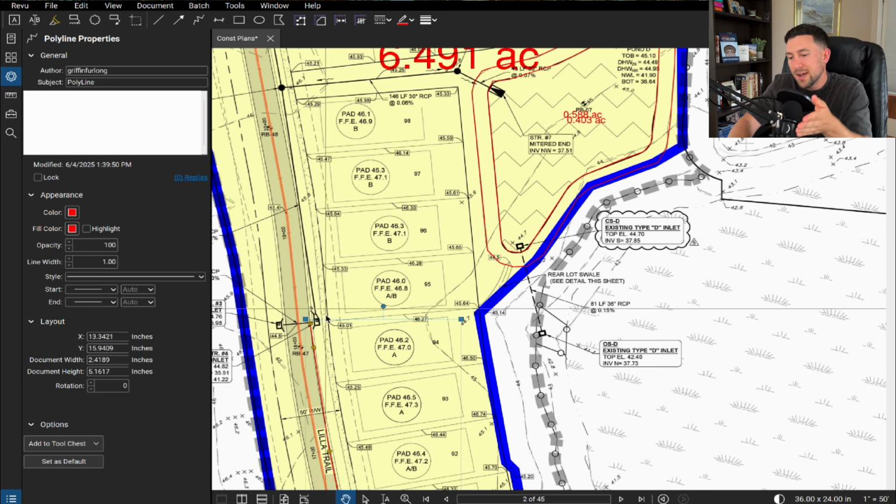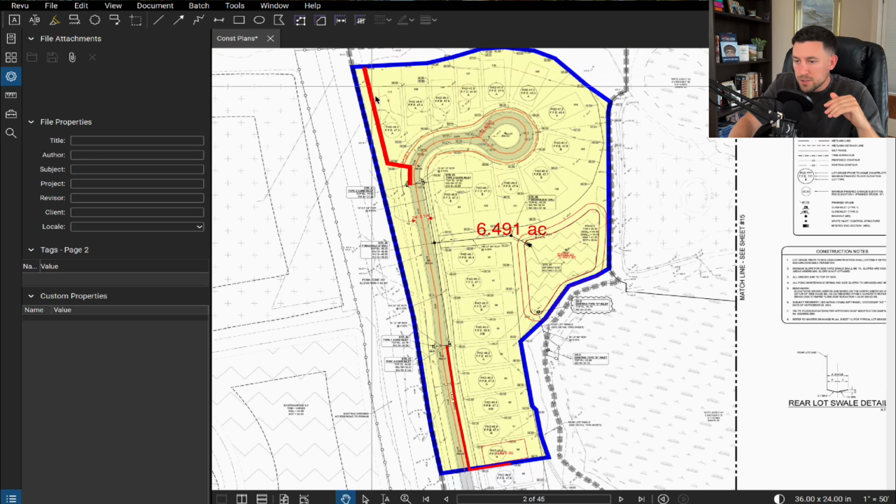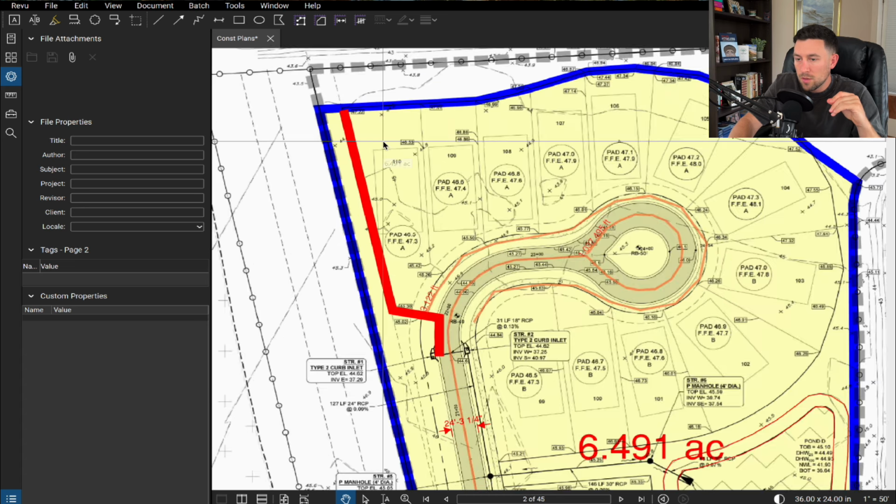And a lot of times I don't factor in the travel time in the pipes because this system is already submerged with water. This normal water level is already within the storm system. And sometimes you'll have to create a few patterns here and pick what the longest one is. But to me, just from my eyes, it looks like that's the longest. So we're going to go with that one.